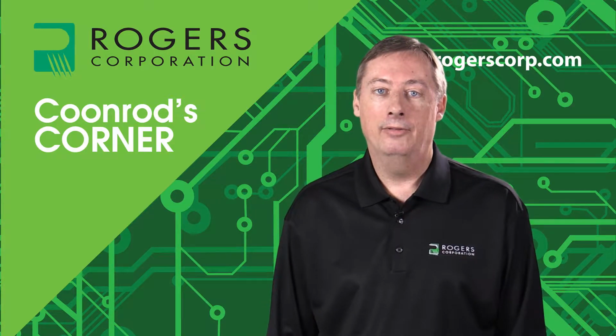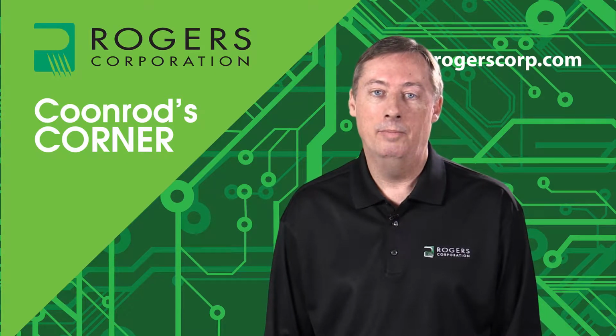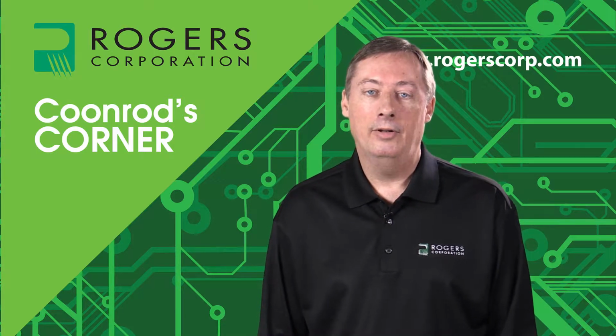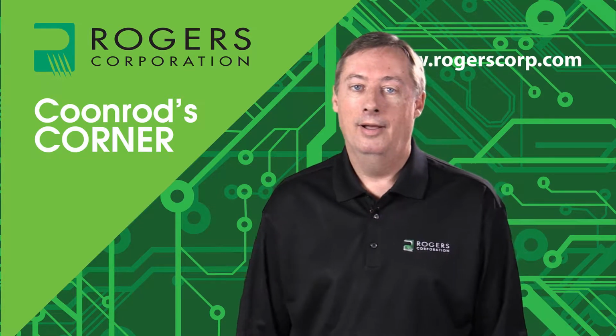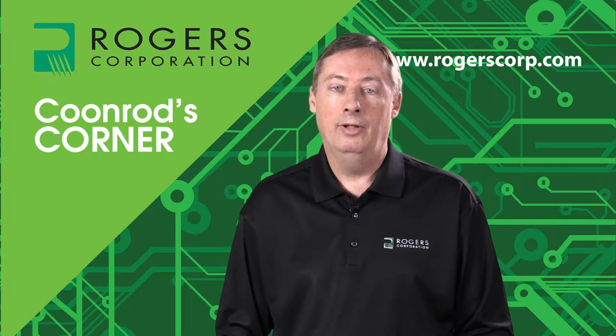Today I'm going to be talking about several different aspects of impedance, and specifically different facets of impedance that designers and fabricators really should understand for optimum circuit performance. Now, there are several different categories of impedance: wave impedance, characteristic impedance, surface impedance, frequency-dependent impedance. There are several different types, and mostly what I'm going to be talking about today is characteristic